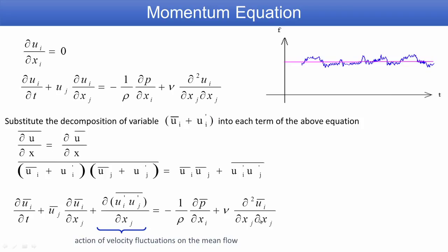What is to be noted importantly is that the first term, for example, is a time derivative term, and this term has the same form as in the original Navier-Stokes equation. The original Navier-Stokes equation has a time derivative term, the time averaged Navier-Stokes equation also has a time derivative term, and this is ūi and this is only ui.